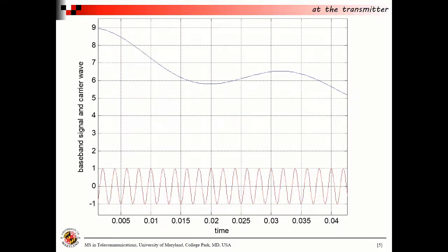As we zoom in, we can see more detail of the carrier, the red carrier at the bottom. So you can see its frequency is about 500. It changes much faster than the information-bearing signal m(t). And we're going to rely on that because the information-bearing signal has to be carried over the envelope of the AM signal.